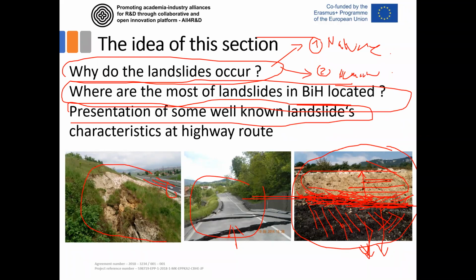But when we are dealing with landslides in Bosnia and Herzegovina, I believe similar conditions are not worldwide, but definitely local in this area, you will see that most of the landslides have such a mechanism that the soil-like material slides on the contact with the rock, and the main trigger that brings some slope into unstable condition is the water level, actually the increment of water level, of course in combination with the human factor, with some excavation and additional load on the slopes.